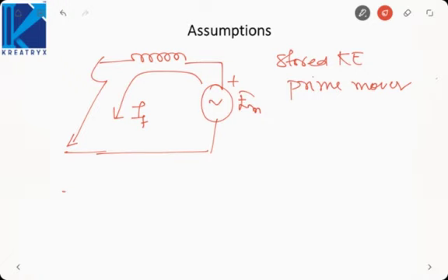So if we neglect the synchronous motor, then what will happen? We are neglecting a part of the fault current. That is, we are underestimating the fault current, which is not a healthy practice. So we will consider the synchronous motor as it will act as a generator. But we will neglect the induction motor.